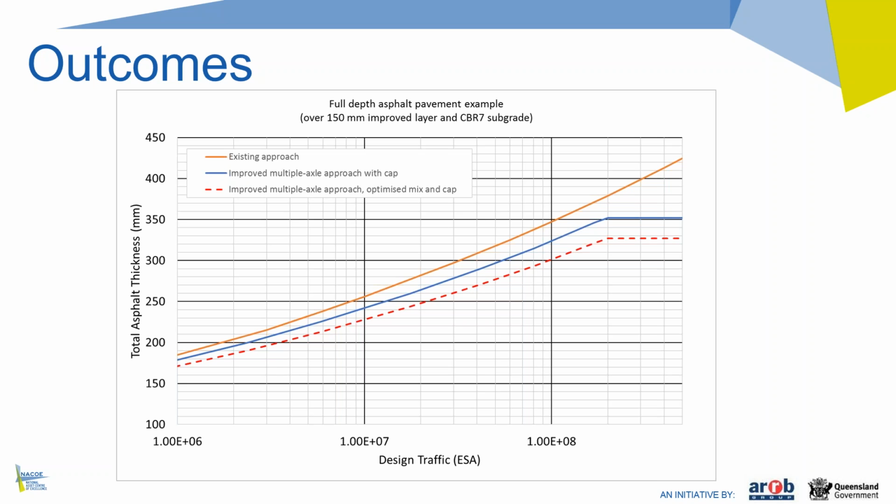And that difference, or the savings, should be achieved immediately with the new technical note, and that's even without considering the mix-specific aspects of the method that Eric covered yesterday. Optimising mixes for fatigue performance should lead to further reductions in thickness, somewhere below that middle line, and the bottom dashed line there is to illustrate just where that could be for the right mix if it's properly optimised for fatigue performance.